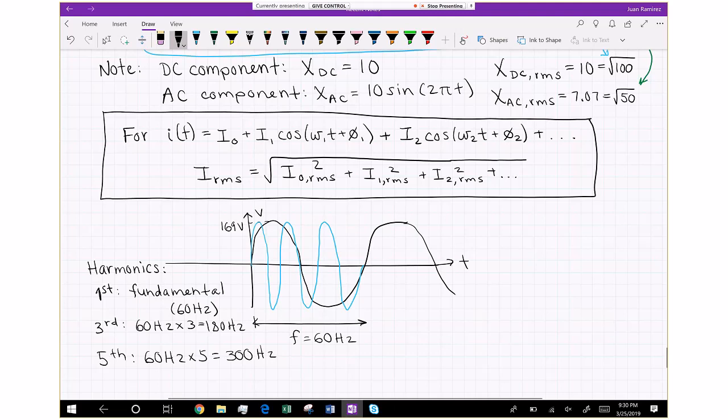All right, so that's maybe a little bit more background than what you need to actually get going on some of these examples and problems, but I definitely encourage you to take a stab at a few of them. Sometimes you'll get them in the form of a graph, and you have to first convert that graph into a time domain expression, and then find the RMS value that way. Or if you already have the expression, then you just plug it into that formula. And remember to use those tools that we uncovered for the 3 different cases: a pulse waveform, a pure sinusoid, and a sinusoid that has different frequency content. All right, thank you very much.